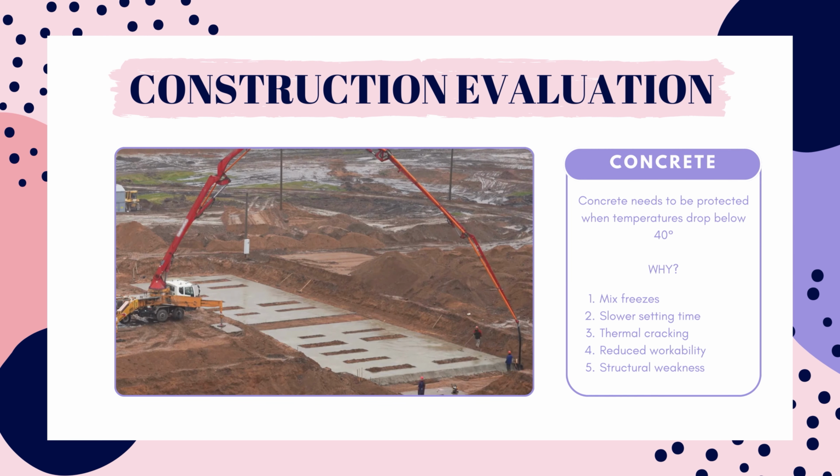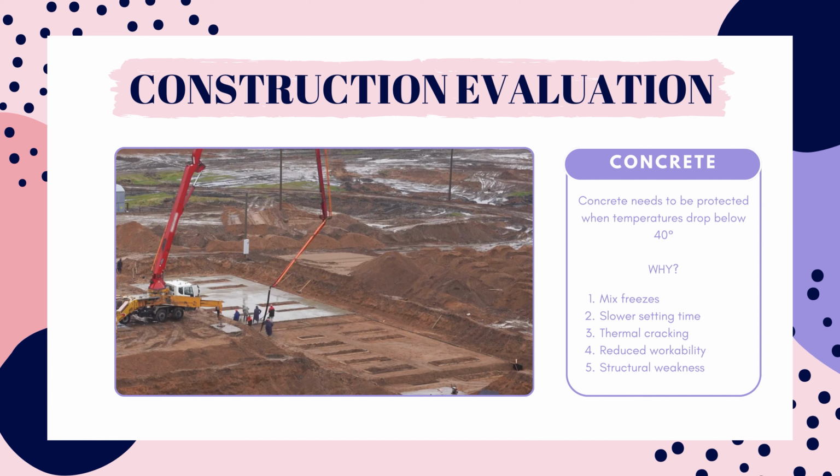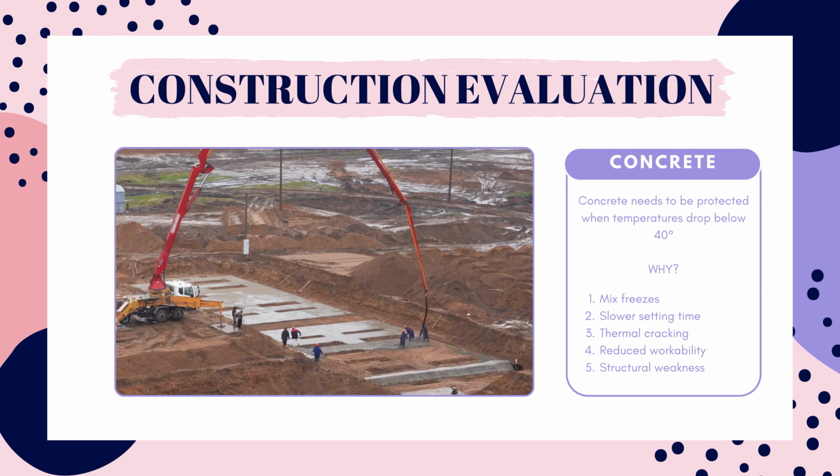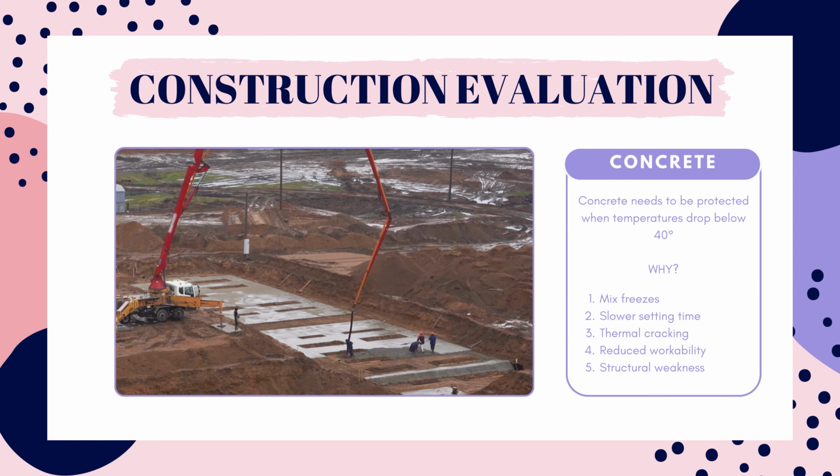Pouring concrete in very cold weather and then exposing it to sudden temperature drops can lead to internal stresses within the concrete, resulting in cracking. Cold temperatures can also reduce the workability of concrete, making it more difficult to place and finish properly. This can also lead to issues with the surface finish and overall quality.